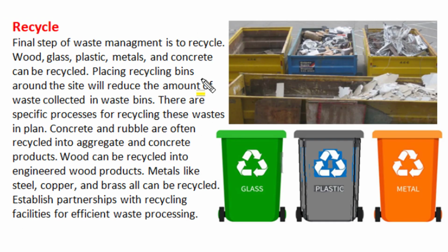With reduce and reuse, recycle is the final step of waste management. Several construction and demolition wastes like wood, glass, plastic, metals, and concrete can be recycled. We can place recycle bins for sorting waste material at suitable positions on the construction site, and this segregation will reduce the amount of waste collected in an unsegregated waste bin.